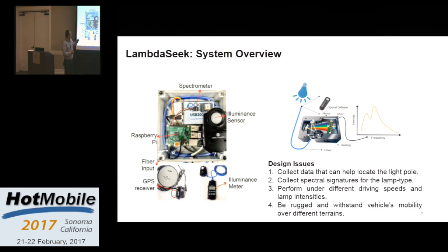And of course, we have a spectrometer. How does a spectrometer work? It has an optical fiber which has a lens at one end. The light goes into it. The light is split up into different wavelengths, and these different wavelengths activate a CCD sensor, which reports an intensity or a count of number of electrons. Again, a proxy for the power content at that wavelength.